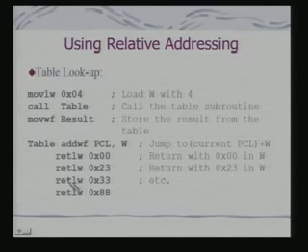What is the instruction from the table? The table is represented as RETLW instructions. So, what does that mean? In this case, you return by loading a particular value onto W. So, a complete table lookup operation has been implemented, and implemented pretty efficiently with pretty high code density.